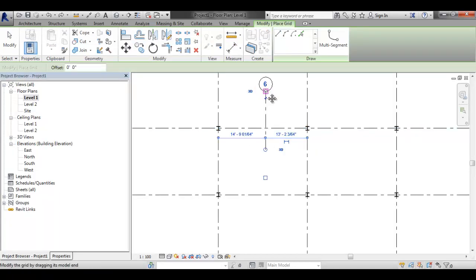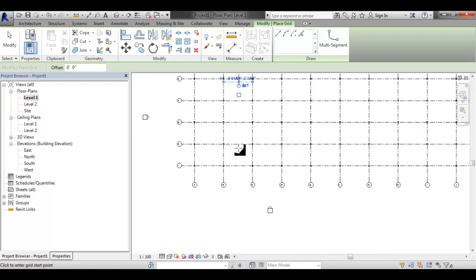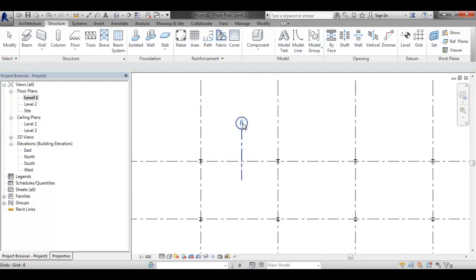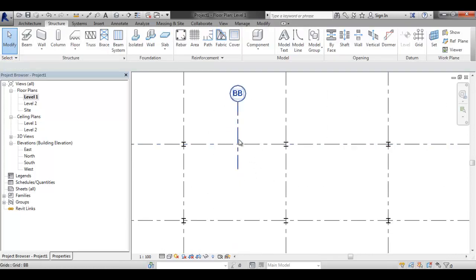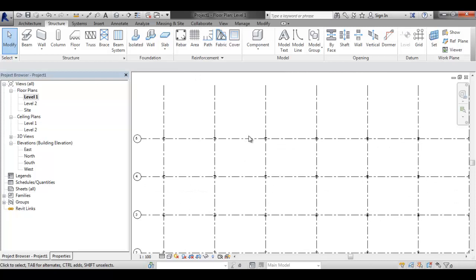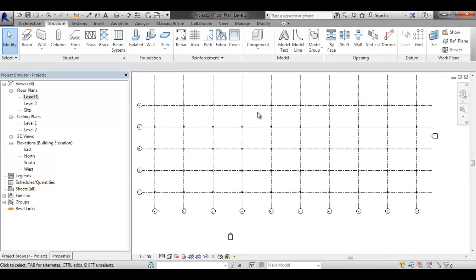And that would be called a double letter. So if I'm between B and C, I would actually call that BB, right? And then I would place another column right there. So that's standards. That's just standards across the board. So that's why I always just do it this way. You don't want to make the engineer mad. They're your best friends. They make all your crazy stuff buildable.